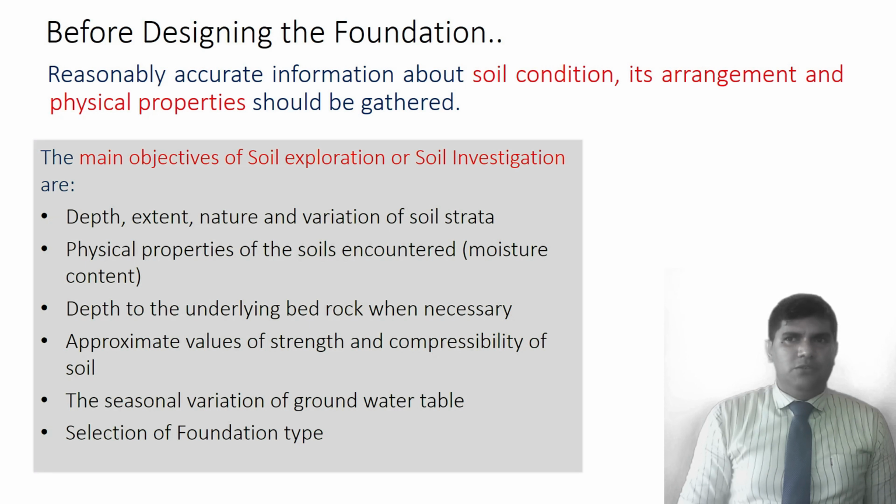If you look at the main objectives of soil investigation or soil exploration, one is that we are going to find the depth, extents and nature of variations of the soil in the particular area. We can take this detail from the borehole. Then the physical properties of soil, the moisture content and particle size, are considered in the physical properties. And the depth of bedrock level, because in a high-rise building we need to know the depth of bedrock, and the water table.